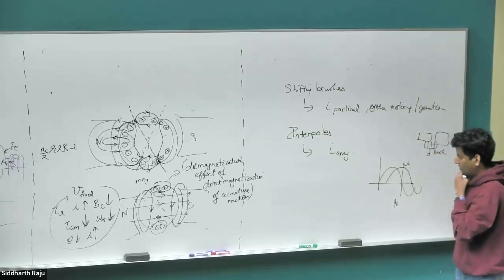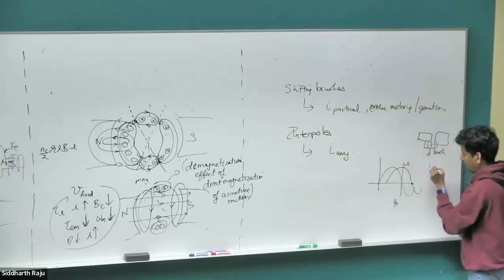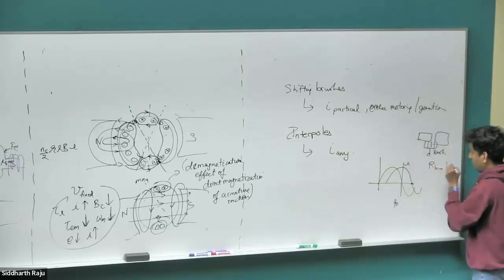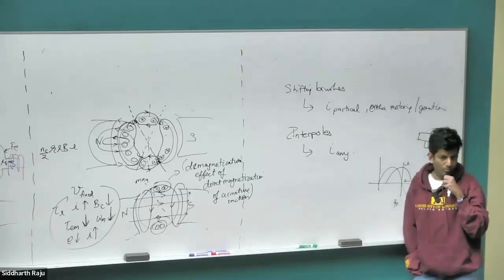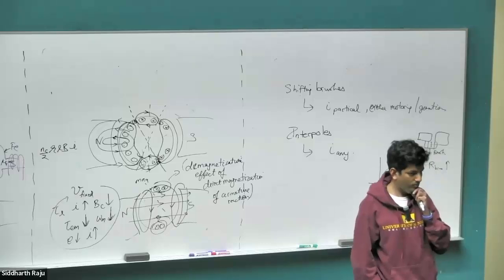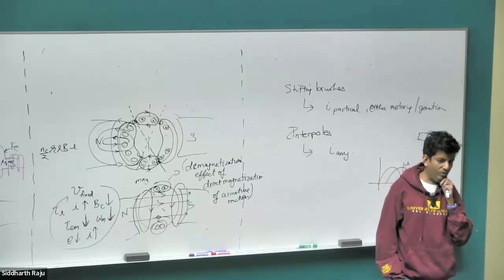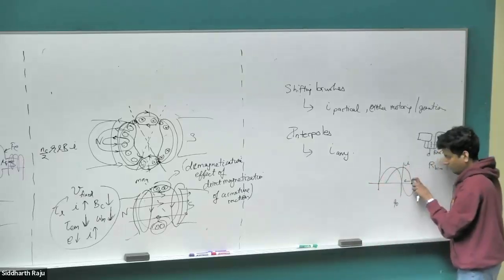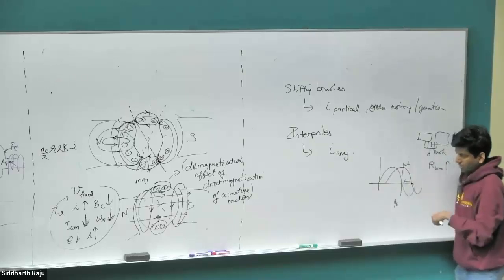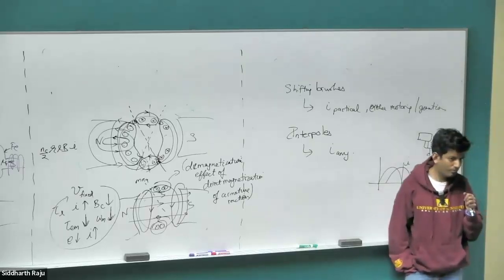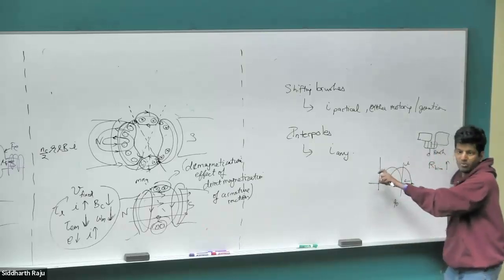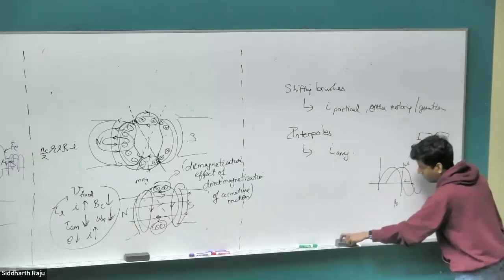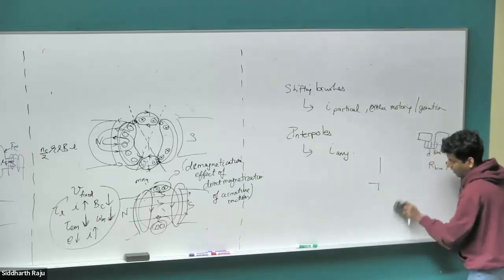So one way we can achieve that is either increasing the resistance of the brush, right, so that this gets closer to this way, or what's another thing that we can do? Is there anything else we can do? I want to shift this current to go backwards. What else can I do? Well, if somehow I can shift the voltage to go backwards as well, I can move the current back for the same given R and L combination.